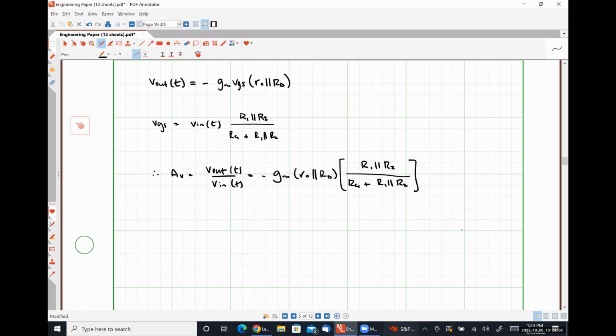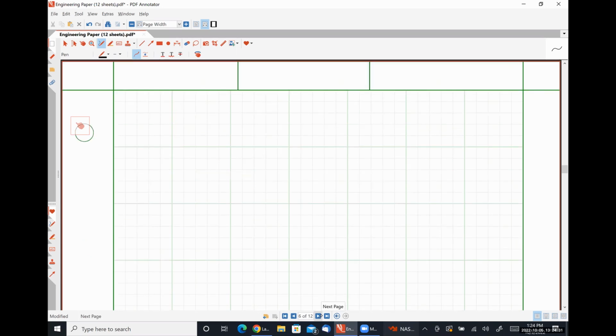So one thing that's interesting about integrated circuit amplifiers is that typically speaking, we don't use capacitive coupling to put our input signals on there. We would actually supply a DC voltage with an AC voltage superimposed on top of it so that we don't have to worry about that biasing stuff there. Not to say that we can't capacitively couple or anything like that, but it's typically not done, okay? So instead, what we would most likely see would be something like this.